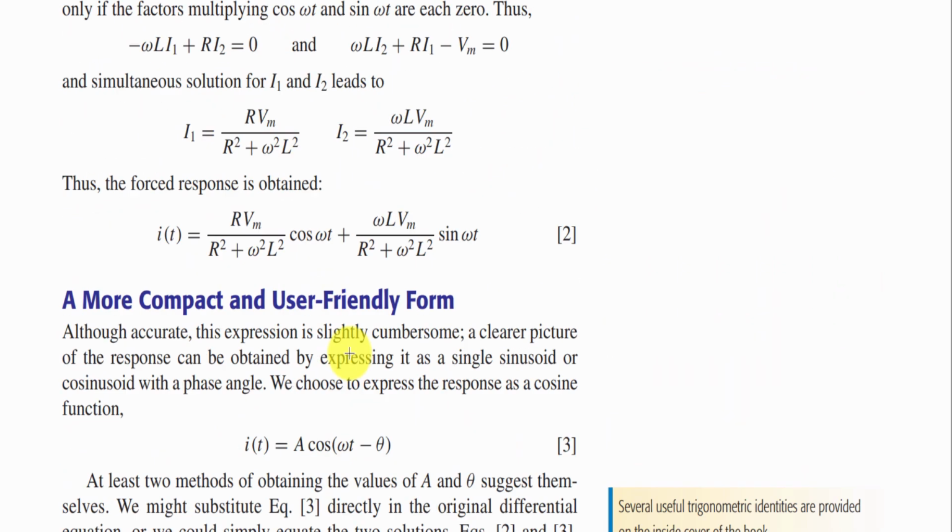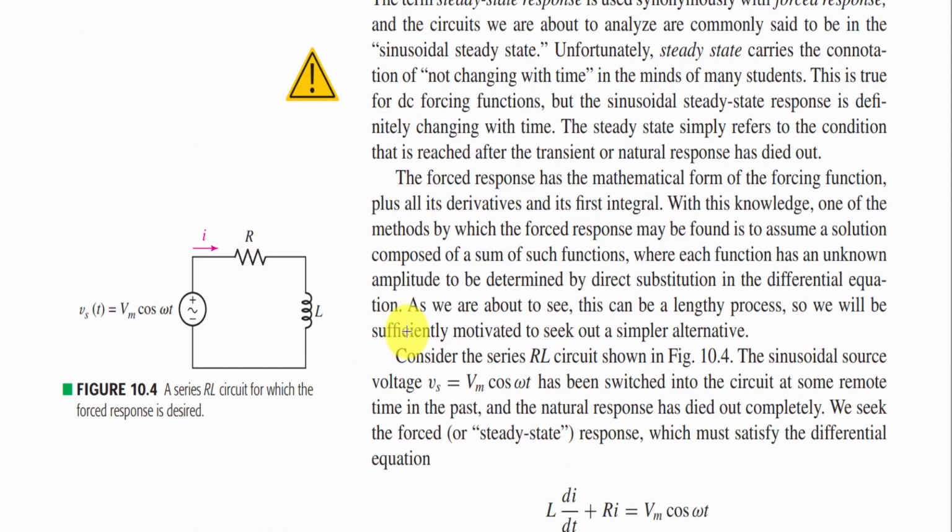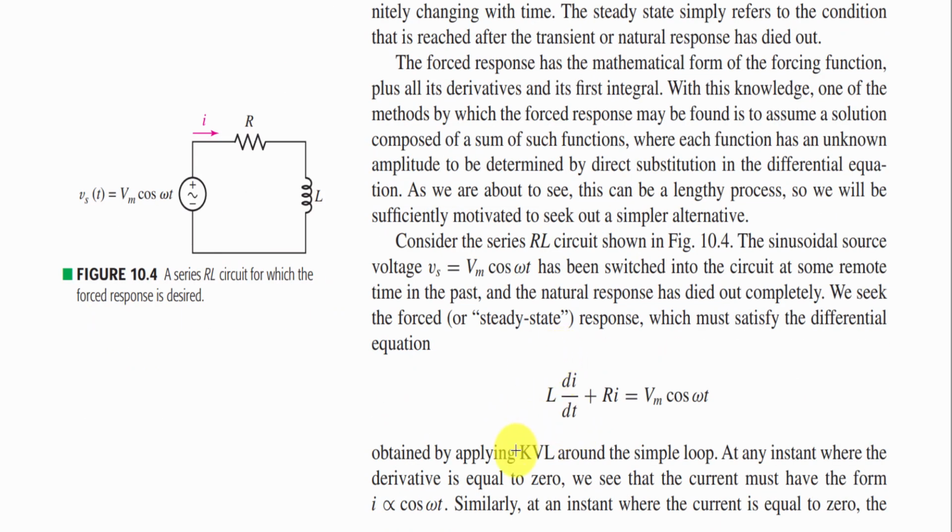You might have noticed that performing the time domain analysis is doable if you have a differential equation. Had there been a capacitor, the capacitor equation IC equals C dV over dt, or the integral of I dt, would have given the voltage of the capacitor, and that would have become an integral equation, and then we could have taken the derivative to cancel out the integral, and that would still become a differential equation.